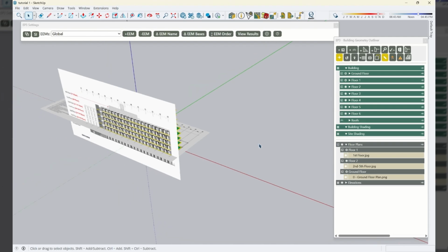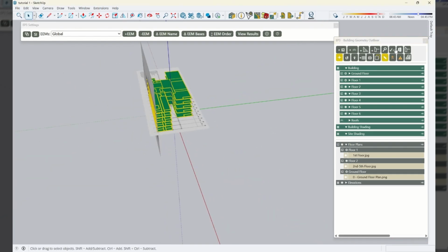Now you may have noticed me every once in a while clicking up on the top here. If your focus has been on one of the dialogues and then you want to use shortcut keys and draw in your drawing space, so if I have the dialogue selected and I hit, say, L, it won't do anything because the focus is on the dialogue.